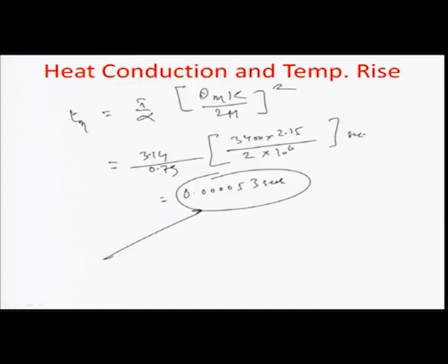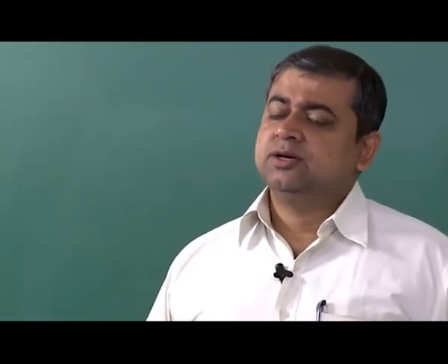So, you can think of the amount of laser power being utilized, at just 10% of the laser power. How much power is really important for changing the material properties, taking it to the vapor state, is a very small percentage of how much power is generated within the ruby crystal medium or even a gas laser. So, that shows the difference in the power levels between what is inside a laser torch and what actually gets delivered from the laser torch.